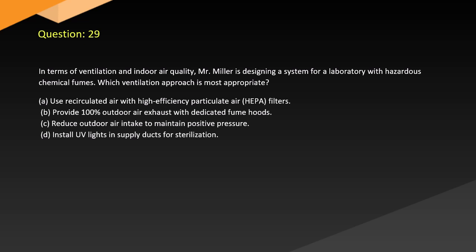Question 29. In terms of ventilation and indoor air quality, Mr. Miller is designing a system for a laboratory with hazardous chemical fumes. Which ventilation approach is most appropriate? A. Use recirculated air with high-efficiency particulate air (HEPA) filters. B. Provide 100% outdoor air exhaust with dedicated fume hoods. C. Reduce outdoor air intake to maintain positive pressure. D. Install UV lights in supply ducts for sterilization.